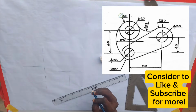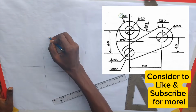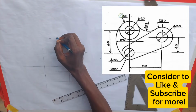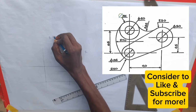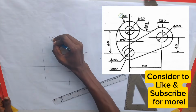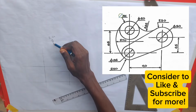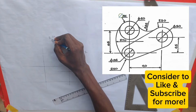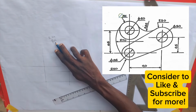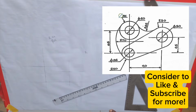Now, let me show you something quickly. Wherever you see something like this in a circle, for example, if you see arrow 20 here, it simply means radius of 20. But wherever you see something like this, it simply means diameter. You know, a line that divides a circle into two equal parts is called diameter. So if you see something like this and 26 like this, it's telling you that the diameter of the circle is 26. Please take note of these two things, they are very important.